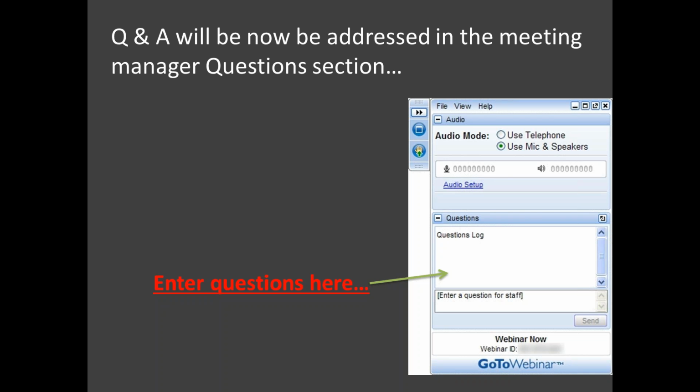But me personally, once I get into a size configuration that's more than half a dozen configurations, I look at making an iPart and immediately putting it in the content center, because you can customize your part number, stock number, description, everything in either an iPart or in the content center. And I personally have found managing it through the content center is an easier workflow for me. Again, this is going to change based on organization and structure.